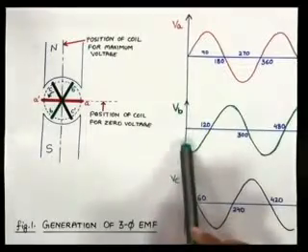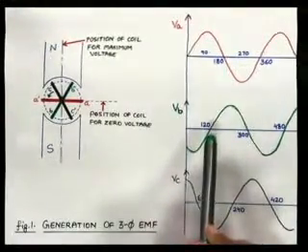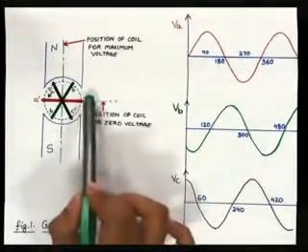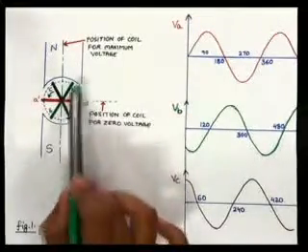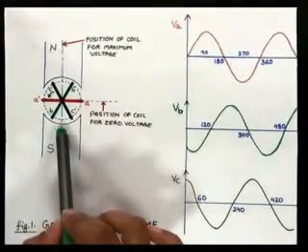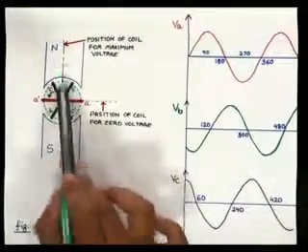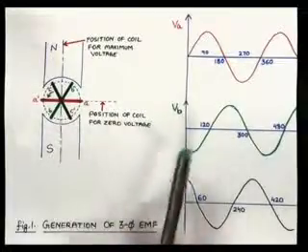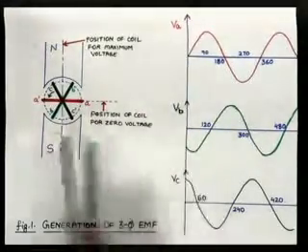So some EMF will be induced, but it will have the negative direction, and it is moving from the rotor is rotating in the counterclockwise direction. So as AA dash starts rotating, BB dash also is rotating. So when it comes under here at this point, so your coil BB dash is in this position, the rate of change of flux linkage is maximum. So maximum EMF is induced in this coil, right?